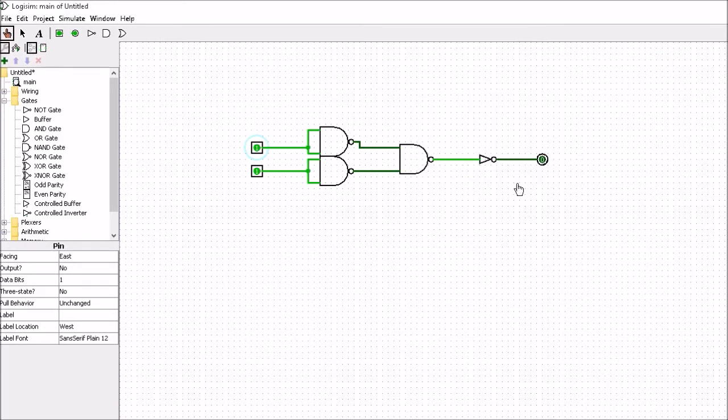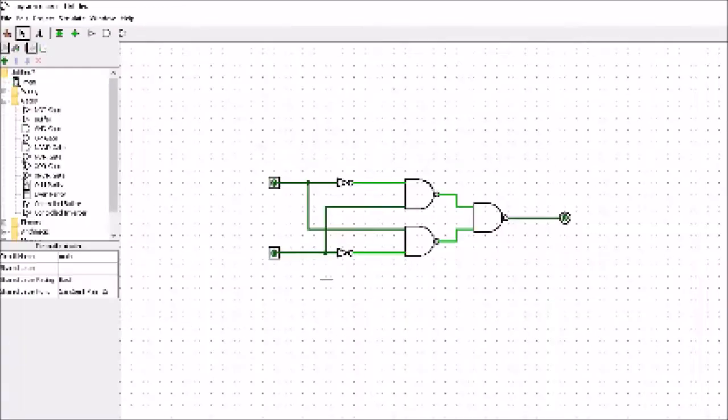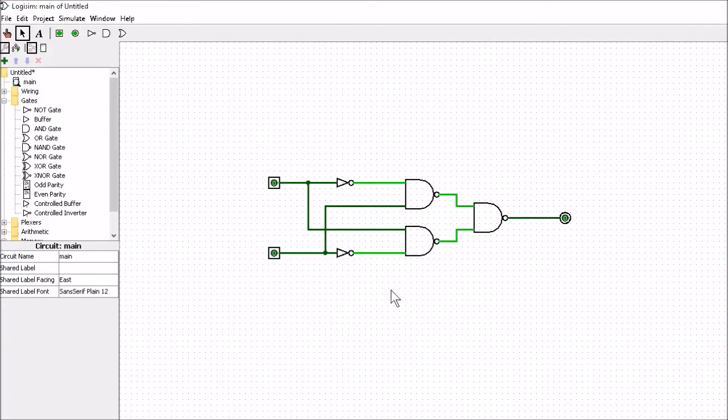So let's have a look at another one. This is our realization for an exclusive OR. We can build an exclusive OR using 1, 2, 3 gates, and if those are replaced by NAND gates, that would be 4, 5 NAND gates. Let's check that it actually works.